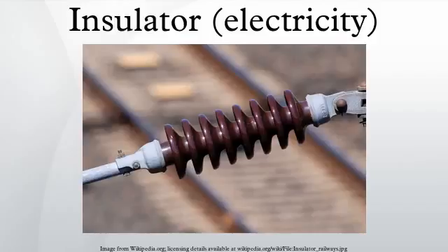Electrical breakdown occurs when the electric field in the material is strong enough to accelerate free charge carriers to a high enough velocity to knock electrons from atoms when they strike them, ionizing the atoms. These freed electrons and ions are in turn accelerated and strike other atoms, creating more charge carriers, in a chain reaction. Rapidly the insulator becomes filled with mobile charge carriers, and its resistance drops to a low level. In a solid, the breakdown voltage is proportional to the band gap energy.